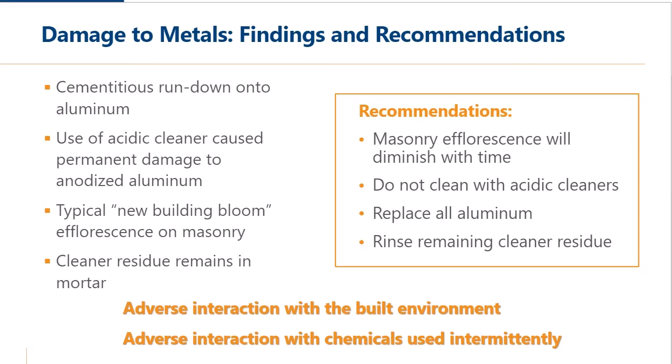So it's not repairable. You can't put more aluminum onto your aluminum. You can't re-anodize in the field. You can paint it to make a uniform appearance, but you have pits and severely degraded aluminum itself that's, you know, going to be in various places and highly localized. So we recommended that they replace it all.